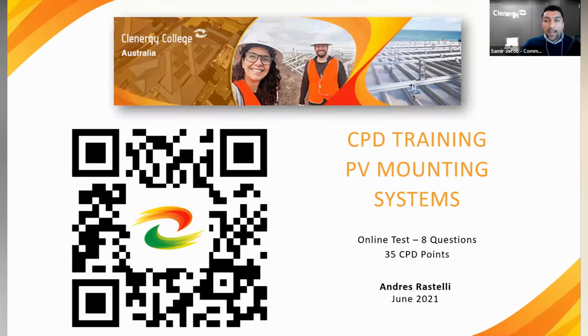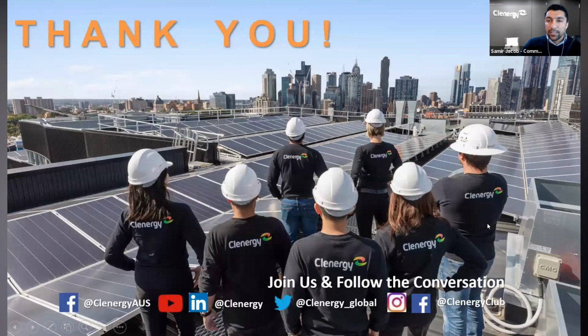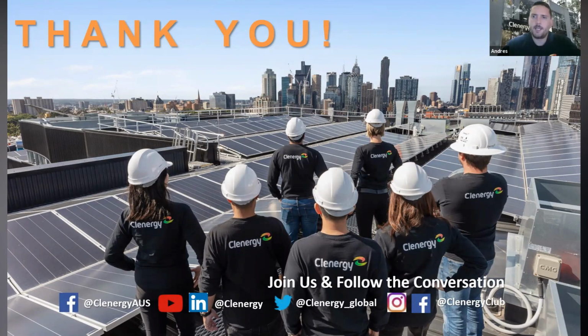Beautiful. I don't think there are any other questions on the Q&A channel, but Andreas, recently you did a live event, I believe in Townsville. What were some of the common questions you got there? Yes, correct. Typical questions were regarding the rail lengths, how to use them and how to design with them. Basically, what do we recommend on ground mounts, how many rows and how many panels could I fit in rows? The short answer is around 30 to 32 panels per row would be recommendable for ground mounts.